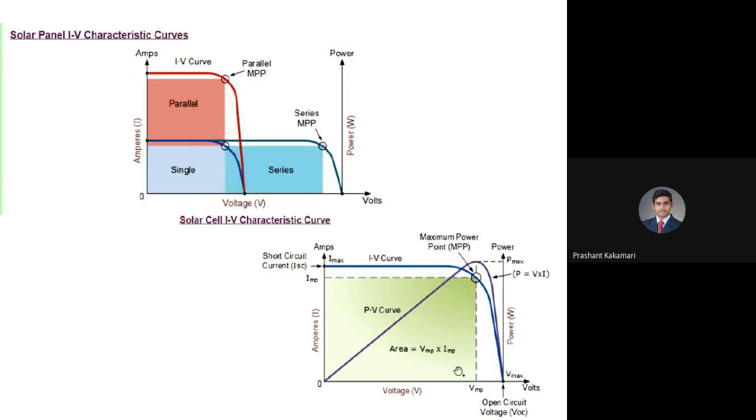Okay, so that is defined by fill factor later. While designing, we have to design for the maximum current and the maximum voltage for the application. This is the maximum power required. But the cell, what will it do? The cell will generate only this much power. So you have to overcome this gap by the efficiency. So you have to improve the efficiency of the cells.